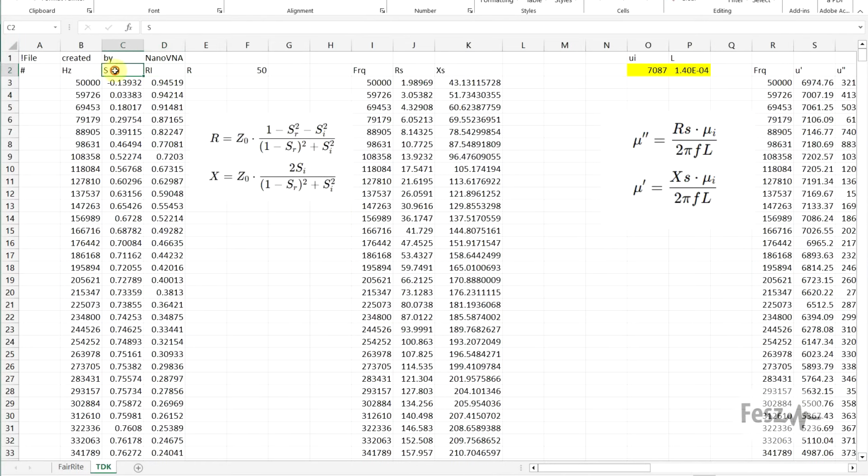For the final measurement, the complex permeability, it's time to do some spreadsheet math. The measurement was done with the VNA and saved as an S11 parameter file, but the actual processing will be done in tables. The coil I used for this was the parallel coil. Now, the VNA that I have saves the S parameters as real imaginary pairs. So the first step is to convert this into series resistance and reactance. Now, if your VNA can save data like this to begin with, you can skip this step, otherwise you'll need to apply these formulas. So that's what I did for every single frequency point.